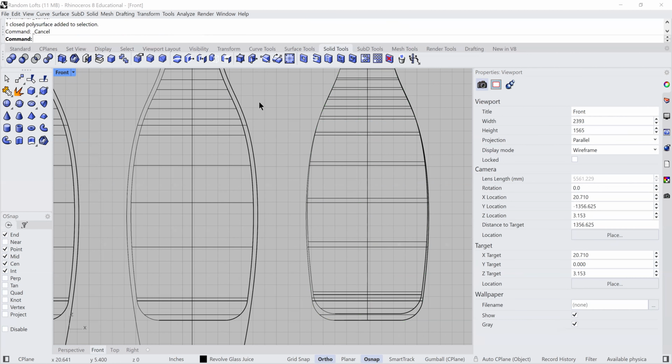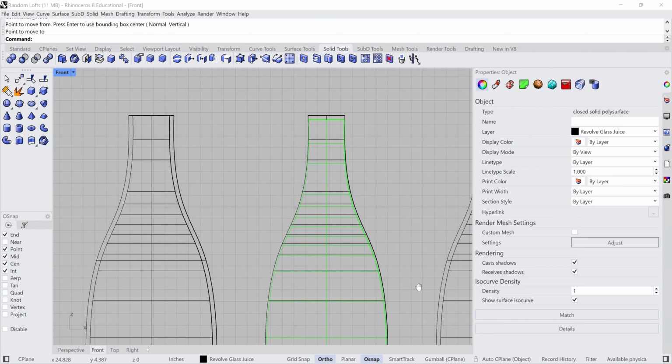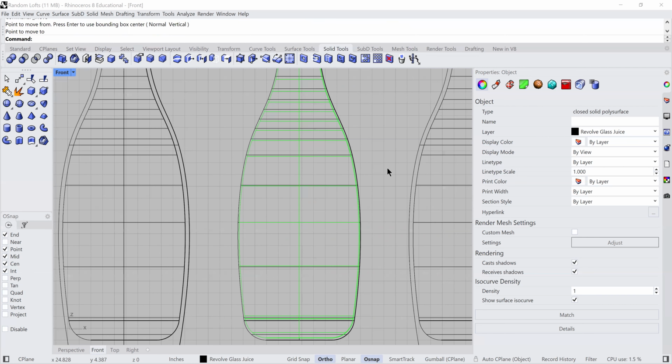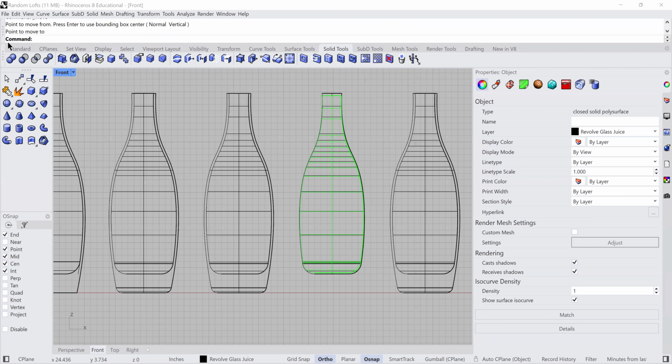So I'm going to move this inside part, which is the part that I had differenced. It's going to move that down. I have ortho on. All right, so that's actually quite a bit, but it's enough to separate that. I probably could have done that a little less. No, that looks pretty good. Okay, so by doing that, I'm going to use this smaller size, and I have that set up over here.